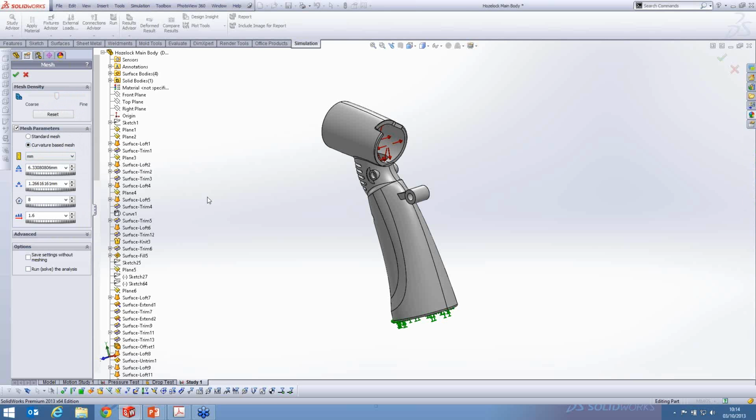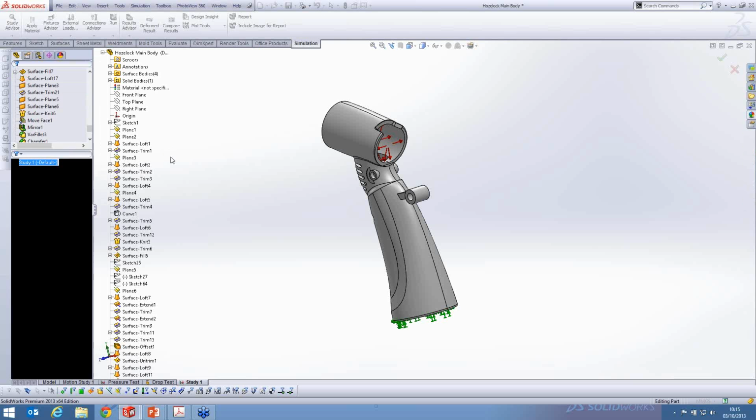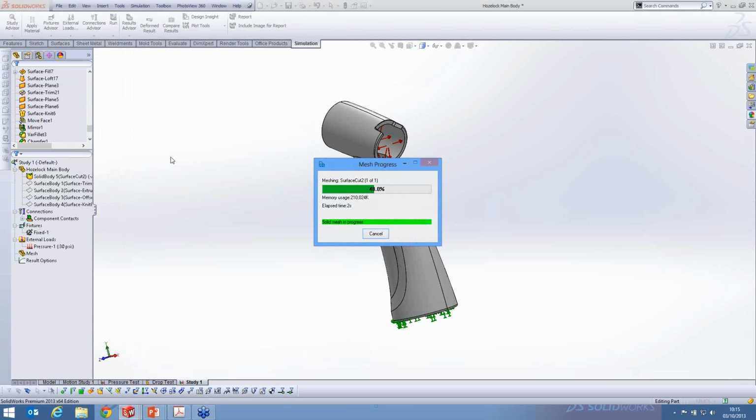We haven't got time to run through that process, so I'm just going to drag this slider along here, and we'll say that we'll have a mesh element size of, let's say, 2 for argument's sake. There is also a minimum size that is linked to that maximum, and we've got some other controls under here, so we can control the number of elements around the circle and also the growth ratio of the elements as well. So if we click the green tick, that's going to go off and generate a mesh for us.